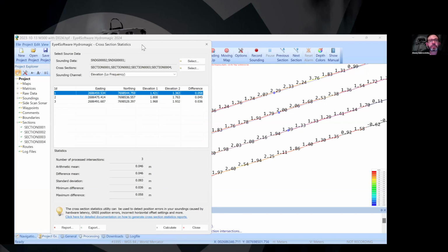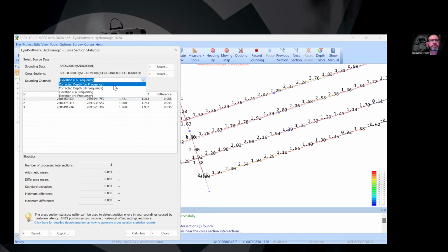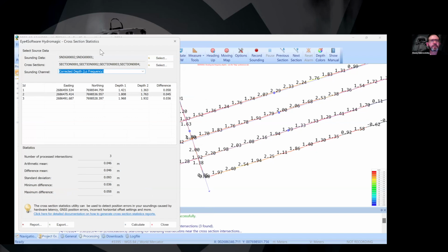It is a very good result because here it is elevation, but if we compare the depth, actually it is... One second, guys. Yeah. So the difference was around 4 centimeters, for a depth of more than 7 meters. That means that the difference is less than 1%. And it is pretty in line with most strict requirements for accuracy of bathymetric surveys.